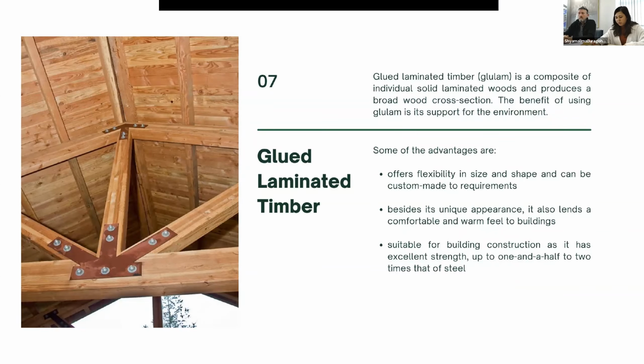Glued laminated timber, or glulam, is a construction material made from layers of wood that are glued together under high pressure. These layers are usually made from softwoods such as spruce or pine and are glued together in such a way that the grain direction of each layer is perpendicular to the previous one, providing a strong, stable,